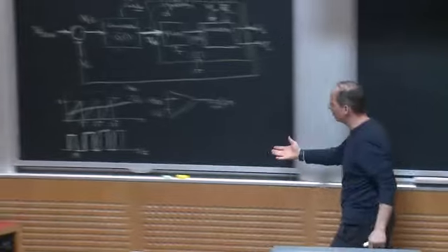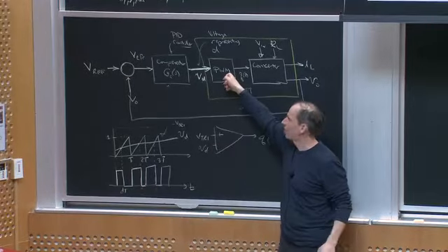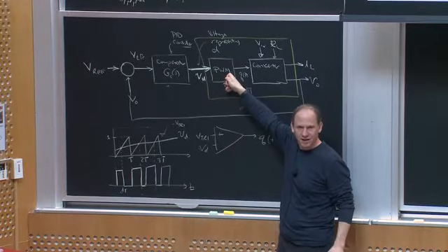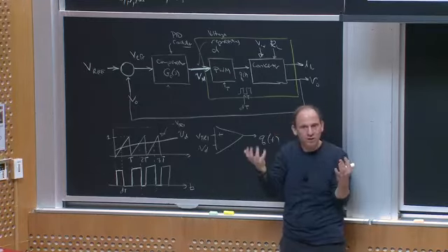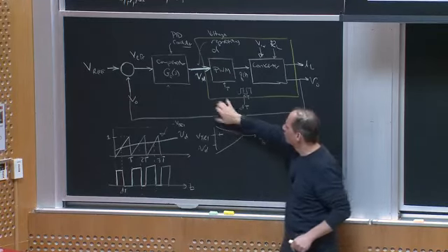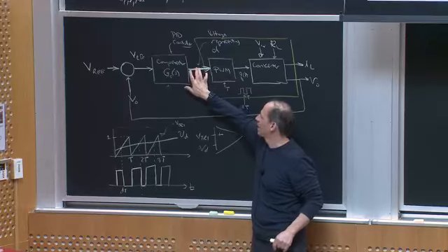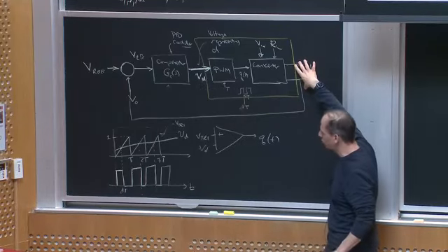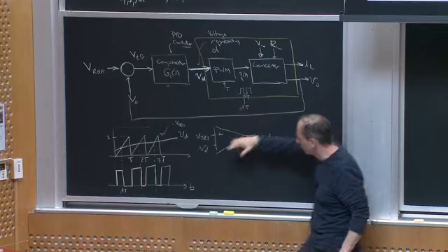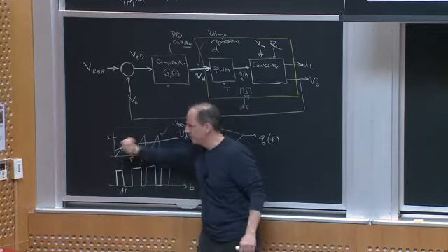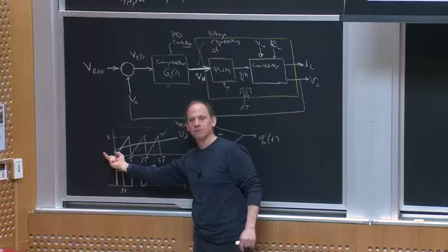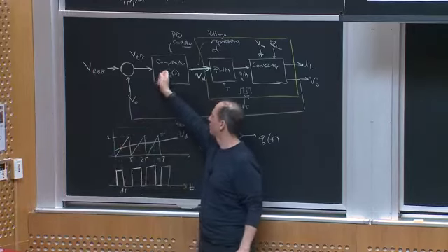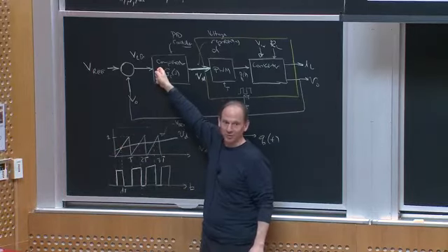Okay? So this is how I build the PWM generator. That's this block here. That's not how I model it, that's just how I implement it. So from a mental perspective, we can worry about going from some desired duty ratio, or the local average duty ratio, to some response, where I'm assuming that VD is only varying very slowly within any given switching cycle. And if your compensator lets it vary very quickly, you're probably going to be unhappy.